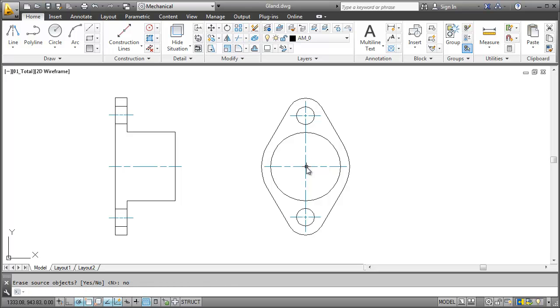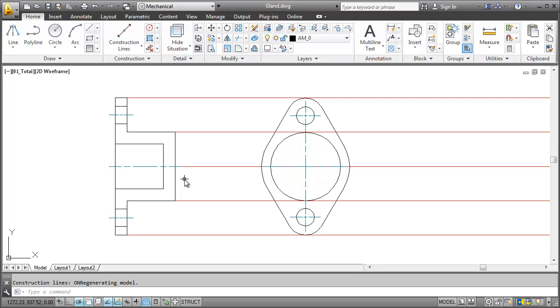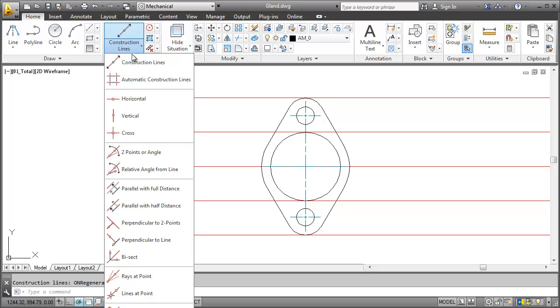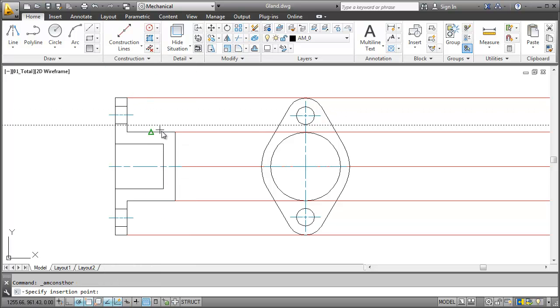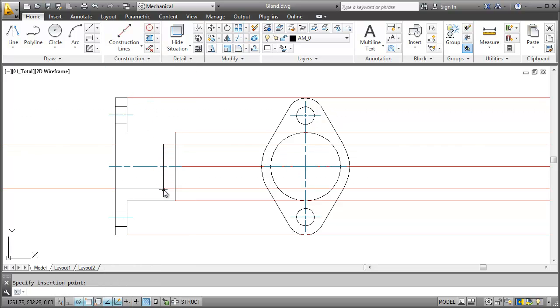In the next step, I'll draw the inner wall of the part. I work with symmetrical lines to do that. First, I select the center line, which defines the symmetry axis. Then I draw one half of the wall, while the other one is automatically created. Next, let's project the inner wall on the top view of the part. I insert two more construction lines and draw the circle.